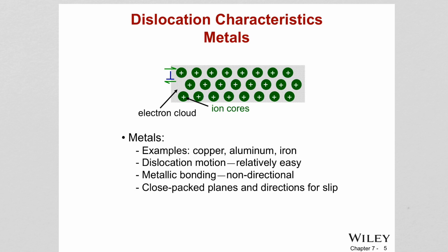It is why strain hardening actually happens. We're going to see that because the number of dislocations increases as we deform the material, and the dislocation density increases, the dislocations will start to interact with each other and prevent each other's motion. Therefore, the strength of the material increases. Think about it: if there are more obstacles in the way of dislocations, you have to push harder and harder to move them.